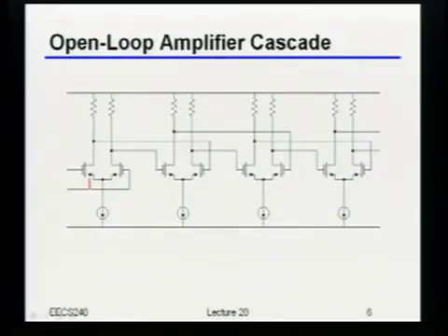So what it actually turns out is that gain and bandwidth don't intrinsically trade off with each other. It's really gain, bandwidth, and delay. Because you can imagine if I have a multi-stage amplifier like this, as I go from here to here, my gain is going up like a power series. If this was, let's say, A, then over here it's going to be A squared, A cubed, A to the fourth, and so on and so forth.